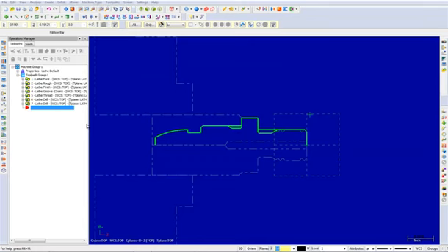In this video, I will demonstrate the necessary parameters used to flip the part. Before we flip the part, we want to ensure our toolpaths are backplotted and verified to look for any errors or changes you may want to make in the program. Verify all the toolpaths as shown.